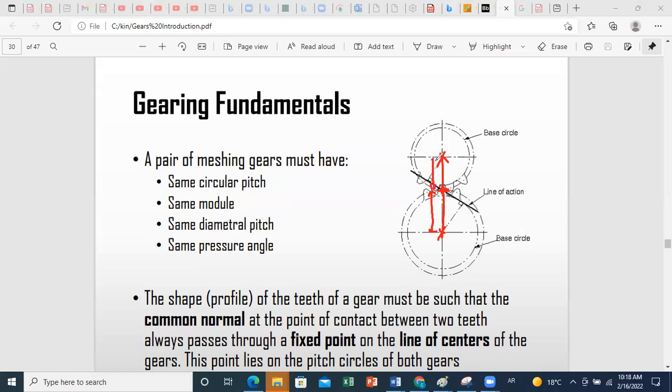The pitch radius is then determined for each gear, and as we said before, it constitutes the circles along which we can compare these gears to two rolling cylinders having a radius equal to the pitch radius of each gear. So we'll have rolling without slipping between the two pitch circles, which can be analyzed as two rolling cylinders on each other with no slipping.